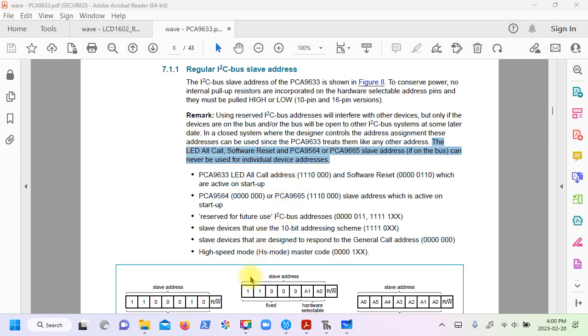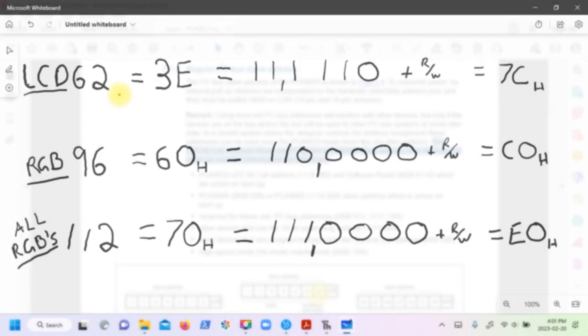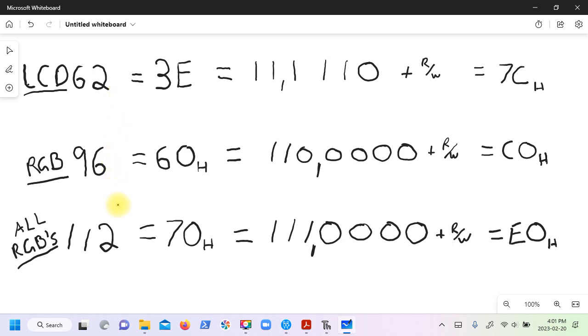Also down here we have our slave address. So this is the other address that's 11000, and A1 and A0 are hardware selectable, and on our Waveshare A0 and A1 are both 0. So this is where the 1100000 comes from. So coming back to our scan list here, you can see that 62 actually ends up referring